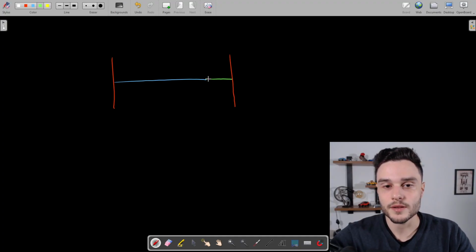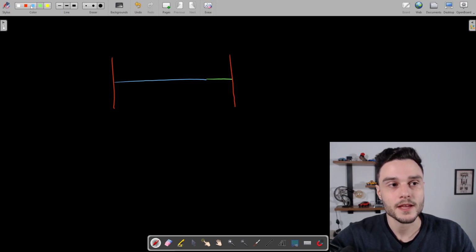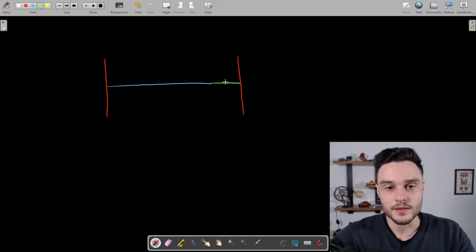Let's suppose, I know that the translator connector doesn't have a length now because we have matched the position of both nodes, but let's suppose that it has this length here, right? Now we apply the translator connector load on this translator connector, right? And then this connector load is going to move these nodes in this direction. And so when this happens, this beam is going to be, well, we are going to have a tensile load occurring on this beam, which is the bolt pretension, right?